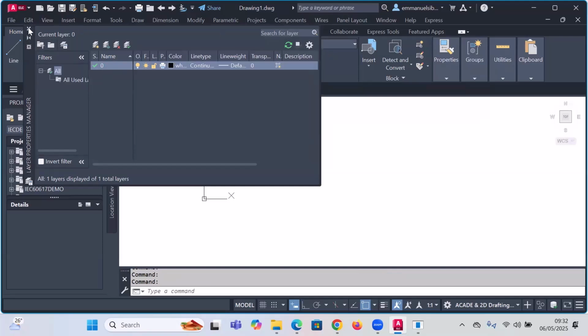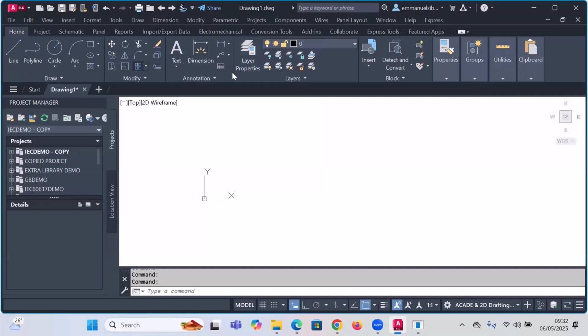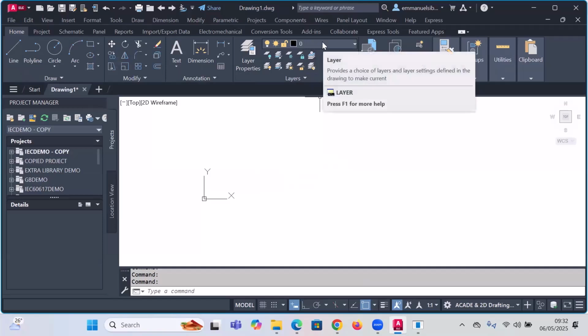Then, if you are creating other layers, they will be below that default. After creating that layer, you can make it the default, so that it is displayed here, and whatever you are drawing here will be in the layer that is displayed here.